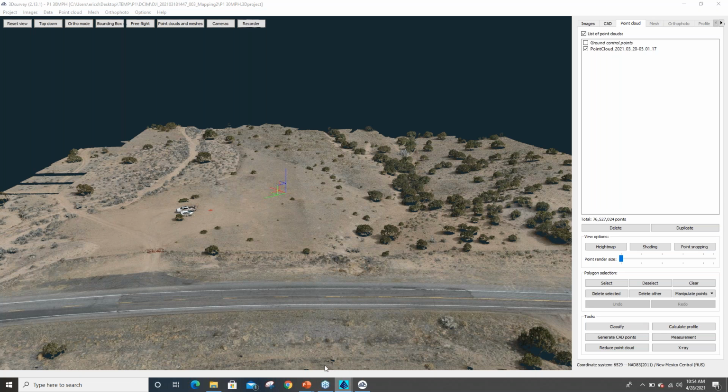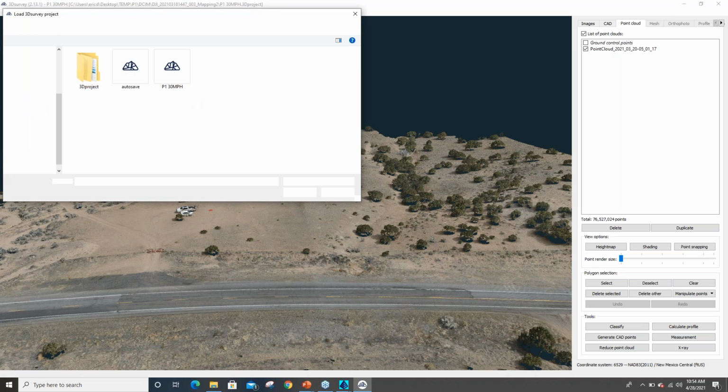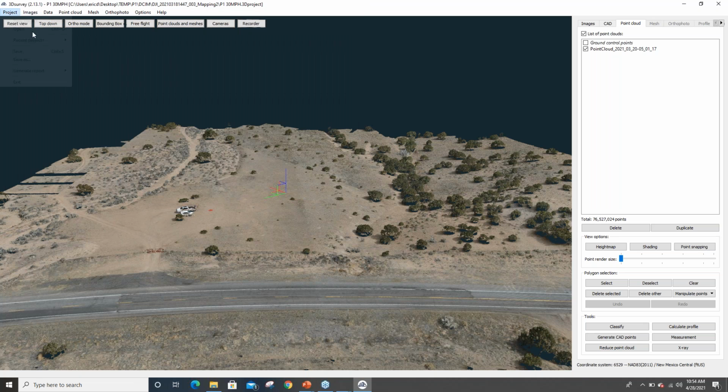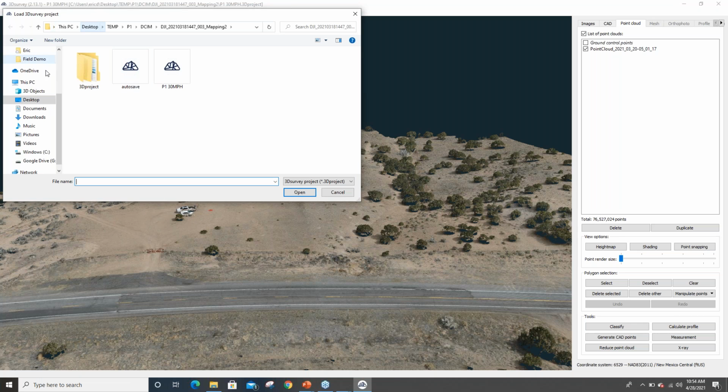Maybe we can try making a new digital terrain model. Let's maybe make it at a 6 or 9 foot grid cell size. Save that one into XML and it should open faster. Okay, let's give that a quick try here. I really want to show the contouring dialog because, like I say, it's at that point that it's just data.